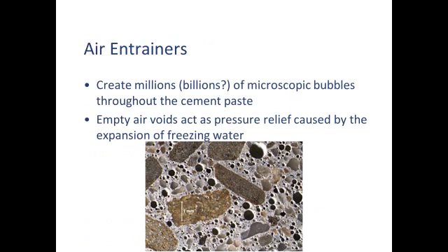Normally, for interior concrete, we never ever have to use an air entrainer. And in warm climates where you don't get freezing temperatures, you don't have to use an air entrainer for outdoor concrete. Where you do is when you have a lot of freezing and thawing, whether that's one time, it gets cold in the beginning of winter and then it doesn't thaw till spring, or in the case where we are here in North Carolina, we get freezing and thawing a lot, where it might be cold and then next week it might warm up, and so we get a lot of freeze-thaw cycles.